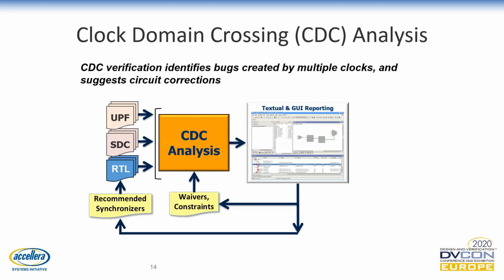Constraints review is another burden on the manual design review process, but this automated flow enables an automated and more thorough constraints review also, in addition to the CDC design review. This automated flow will not only identify errors, but will generate a comprehensive list of all CDC paths and their associated structures for tracking and review.